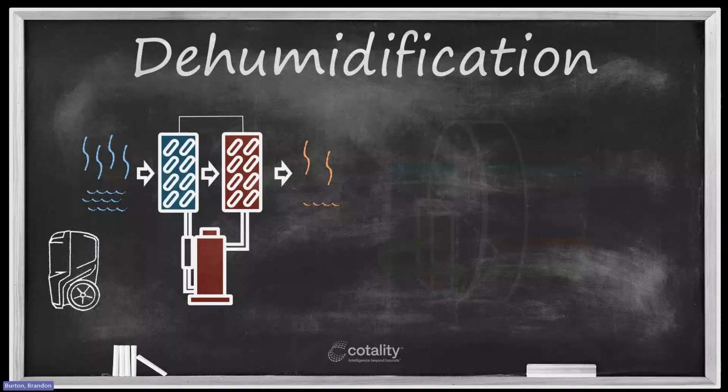This is a compressor or a pump, and what it's doing is pulling refrigerant out of the cold coil, the blue one, and making a really low pressure on one side, and it's forcing that refrigerant into the opposite end, the hot one. The easiest way to understand what that does is to think about concentrating and diluting heat, true heat energy.